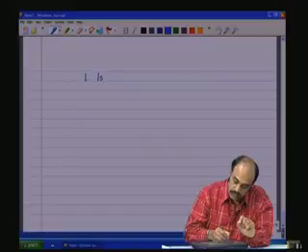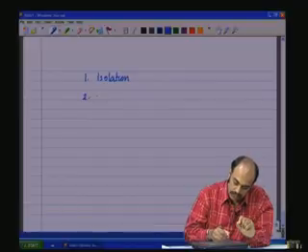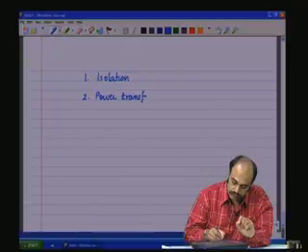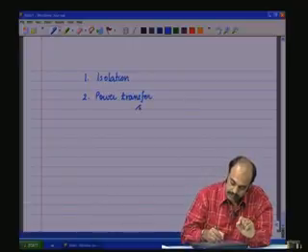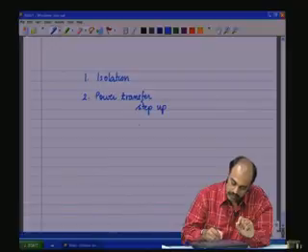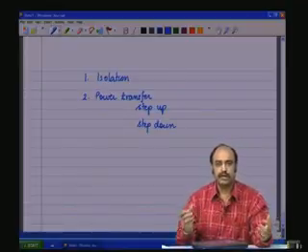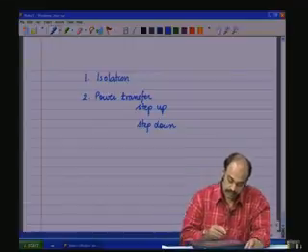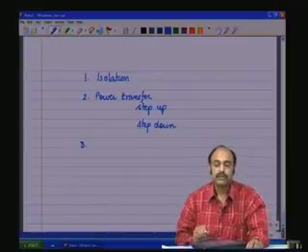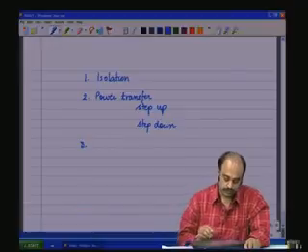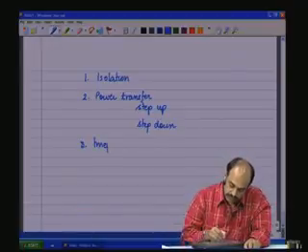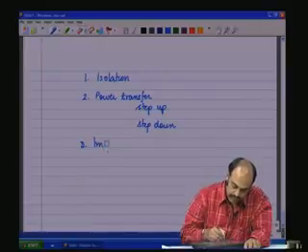It can be used for isolation, and it can be used for power transfer, with step up or step down, to make the voltages and the current compatible between one part of the electric circuit and the other part of the electric circuit. There is another important function that a transformer can do: impedance matching.